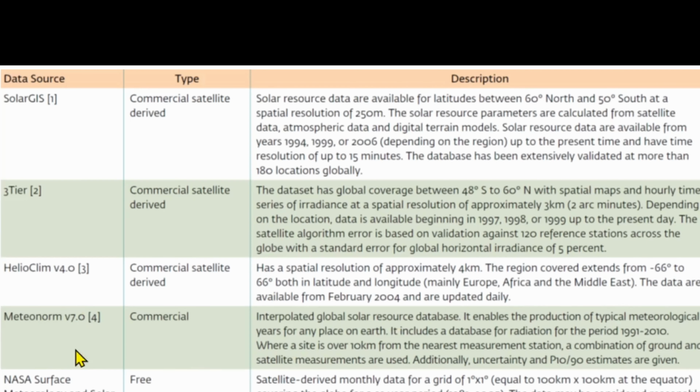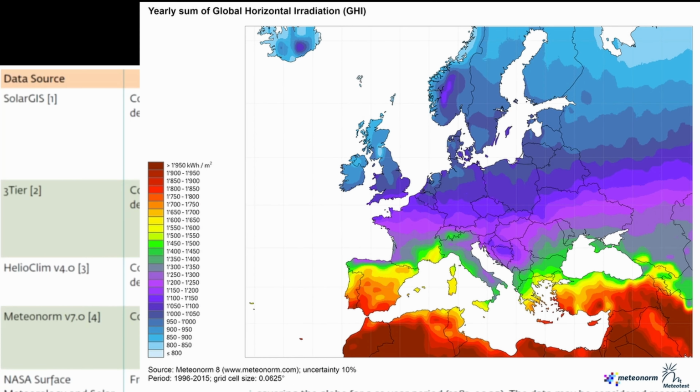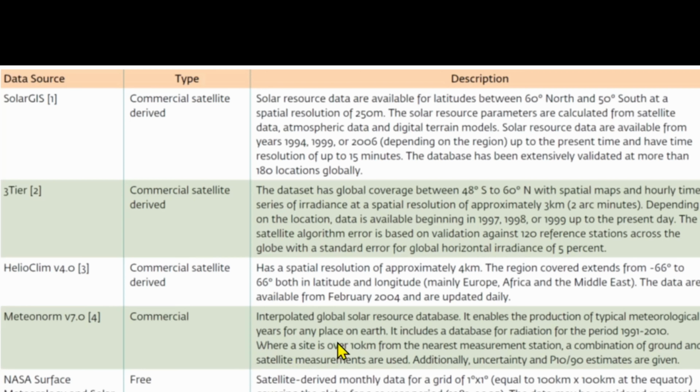What is very often used is the Meteonorm database. This is specially made for photovoltaic applications. So you can even have some tilt angles there, and they calculate the irradiance on the tilt angle and divide between direct and diffuse irradiance in case you have concentration applications, and you can look it up on the website. I think the actual version is 8.0.